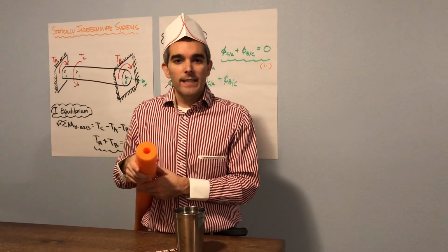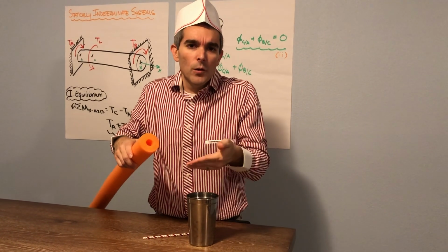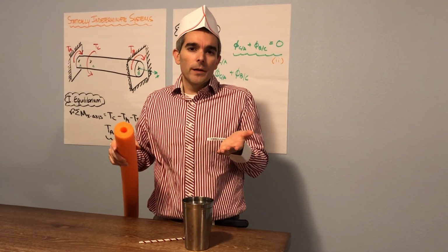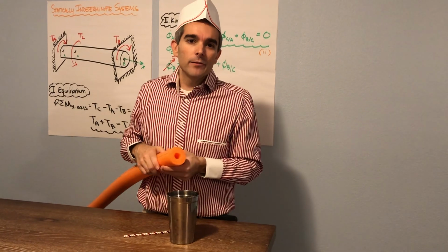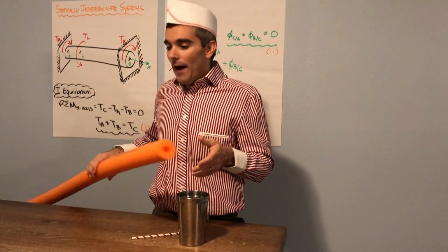So the torque in the steel shell plus the torque in the core would have to equal the total torque applied. Set their angle of twist equal to one another, and you can get the relationship between the torques.